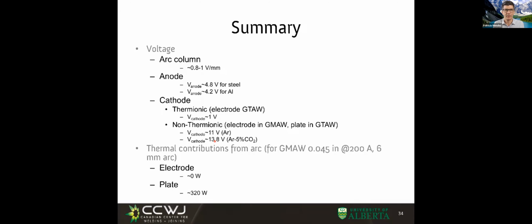And then with the same current and the same equipment, I flip the polarity and I have 100 amps, but running on electrode negative. And my question to you is, in MIG, I don't control the current. I control the voltage. Let's say the voltage will be the same, and I control the wire feed speed. Which one of these two processes, the electrode positive or the electrode negative, is going to need more wire feed speed? Which one of these is going to give us higher deposition rate? I'd like to hear your thoughts.